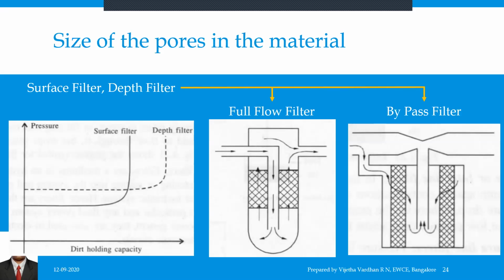As the main flow passes through a venturi, a localized low pressure is created, and this pressure difference across the filter causes a proportion of the fluid to be drawn through the filter. Hence the proportional flow filter is also called a bypass filter.